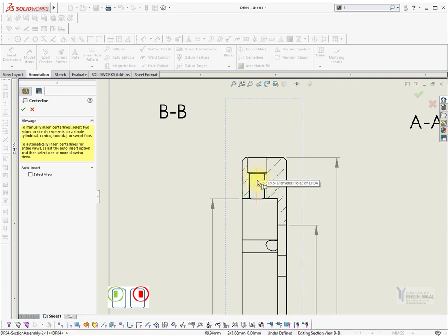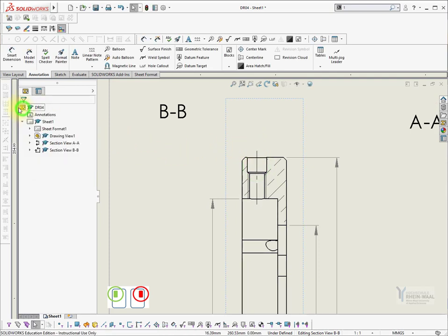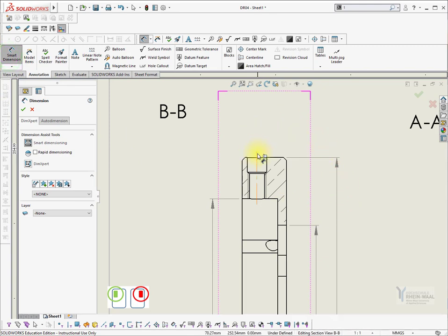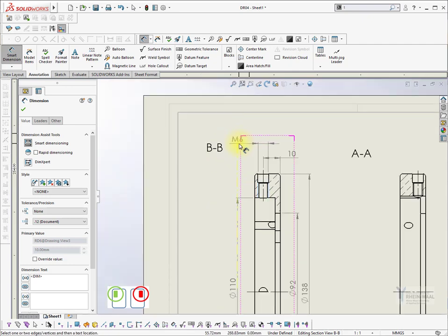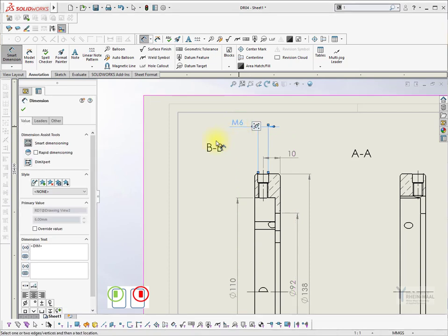First add the forgotten center line. Then go on dimensioning, completing description of hole position. Then describe the hole itself. Add some text to indicate that this hole appears 4 times.